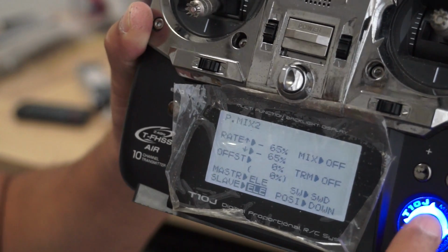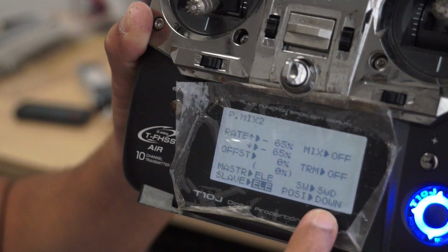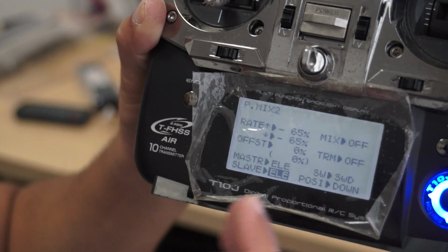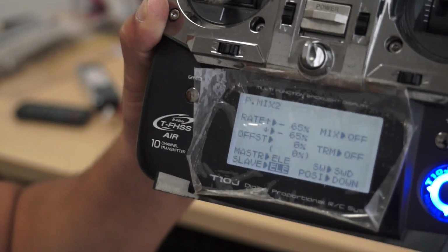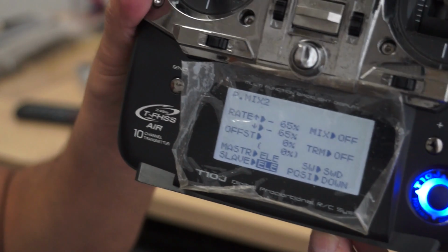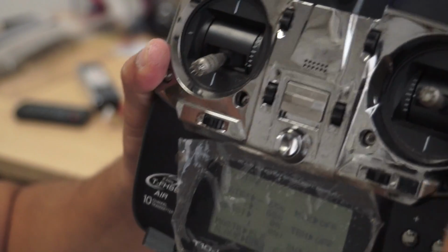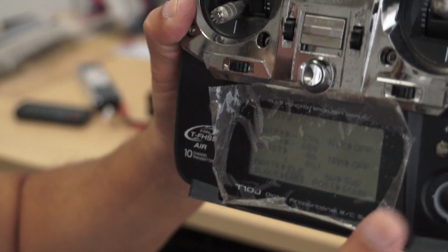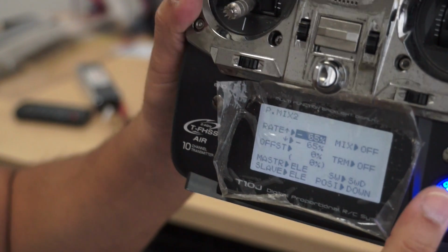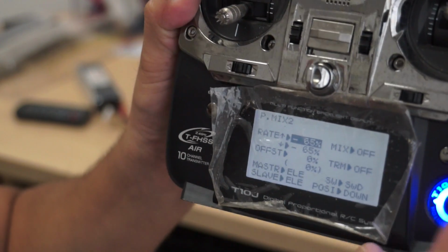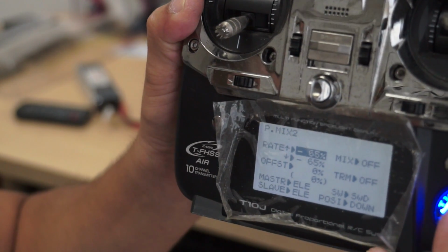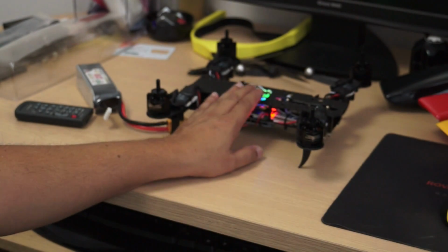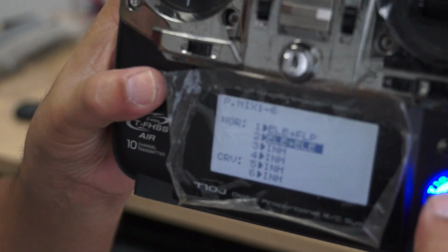We will set another switch for it, that is switch D, because sometimes you might want to use this mix, sometimes you don't. So you can leave yourself a choice whether to use it or not. You can easily turn it on and off together with the first mixing, that is the rotor tilting. So what I did was I added the values in this one, minus 65. Now let's see the effect, because you cannot see the effect on the quadcopter here, but you can see the effect right here on the radio.